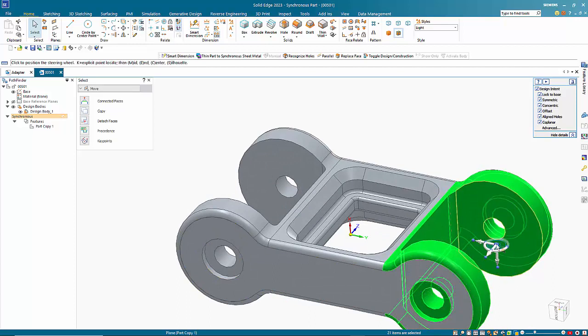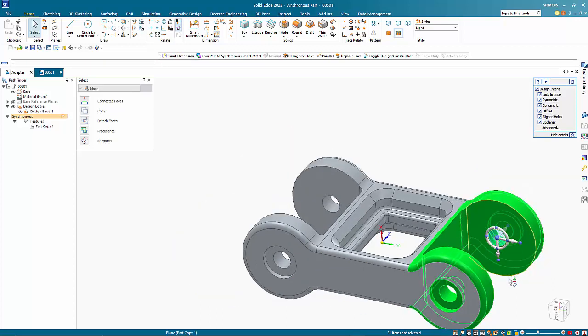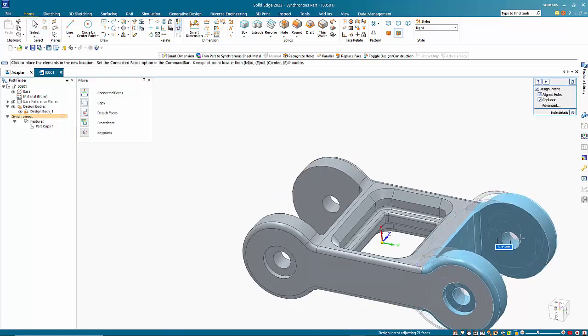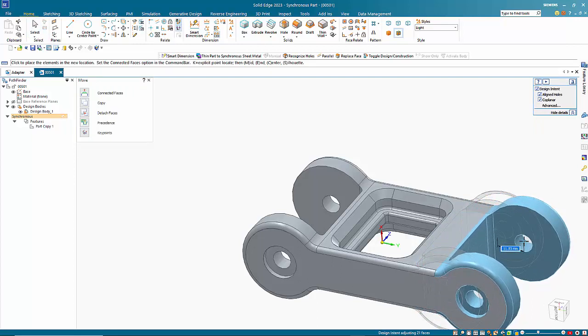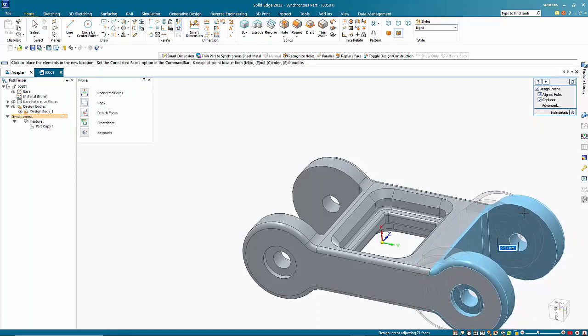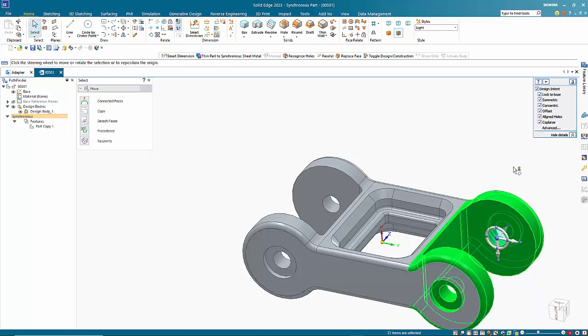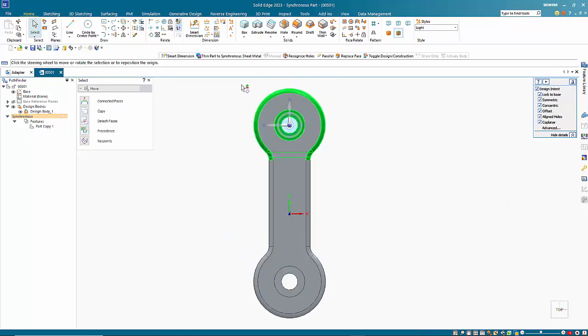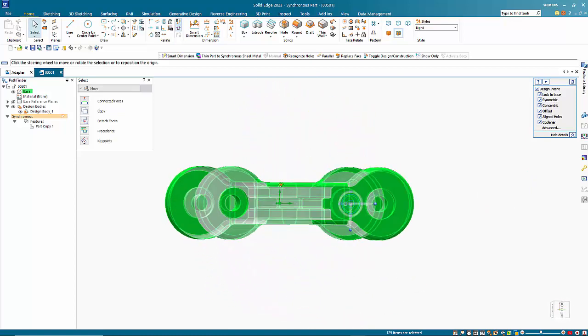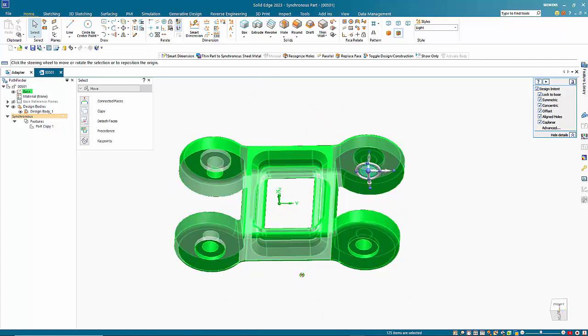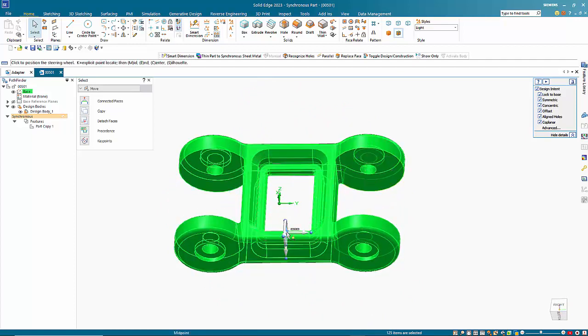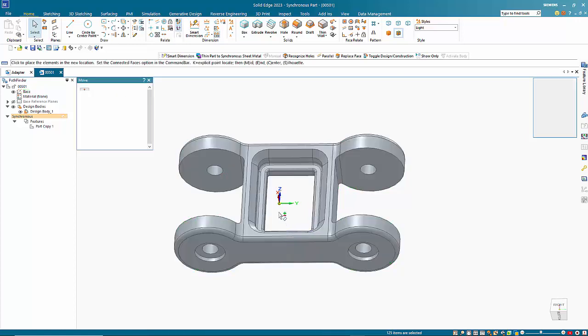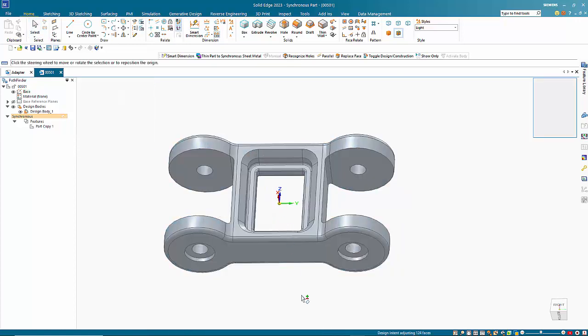The steering wheel has many functions, so you can rotate and move. So you can reposition using the control axis, and you can see that once you've done a fence selection, you can move it. The live rules show you what is currently active. As you noticed, we didn't have any symmetry, and that's because the part is not centralized. So we can use the steering wheel to reposition this using the key points to get it symmetrical.